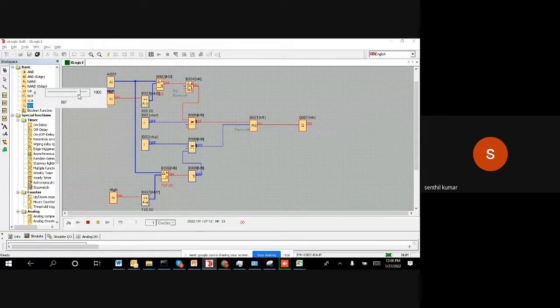So it's gone more than 800. So I could see the motor is running now, right? Right. So let us say the water level is coming down, slowly coming down. And if it comes less than 100, it has to stop. Then at 100, no, it has to stop. It's not stopping, because see, something's wrong with this pulse relay.